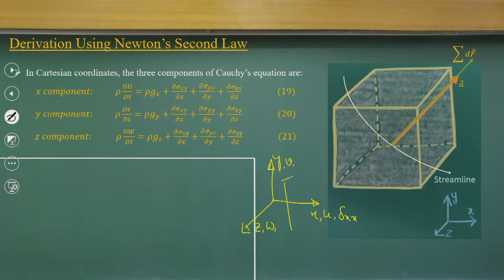You can understand it is acting over this surface and perpendicular to that, which is sigma y x, sigma z x, all three are acting along the x direction. You can take this surface, this is sigma y x, and take this surface, you can look at what is sigma z x. That is what you can notate whenever you sketch the figure coordinates.